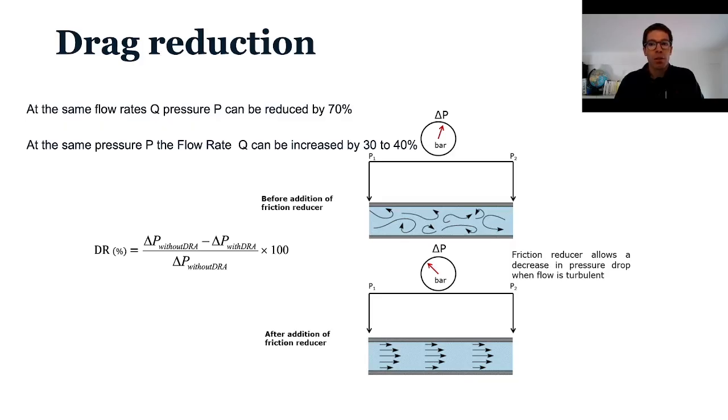There is quite a lot of evidence today, and it's used in a lot of applications. One of them is hydraulic fracturing, where you use polyacrylamides or other polymers to decrease the pressure drops in pipes and the number of pumps used to pump the fluids, and reach much higher pressure rates to break the rocks. This is very important, because we could think that it only works with low polymer concentrations, but as you will see, it works in a variety of cases, even at much higher viscosities.